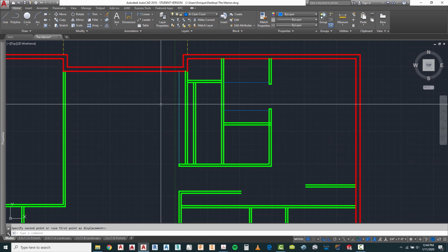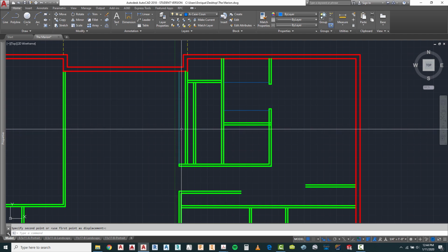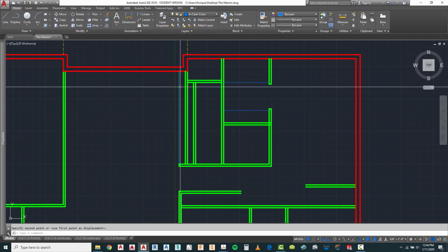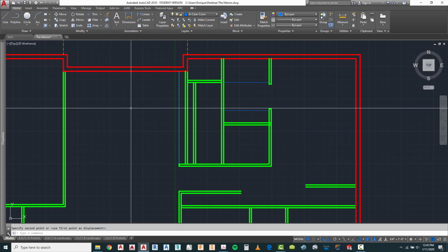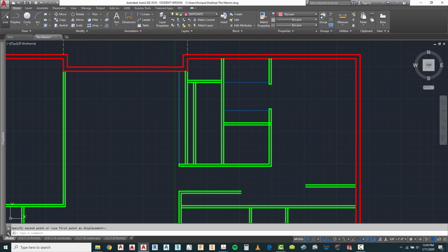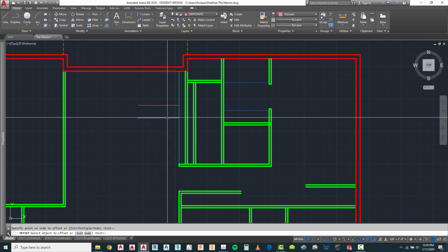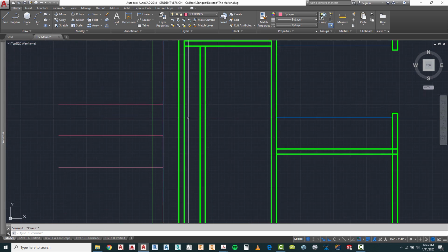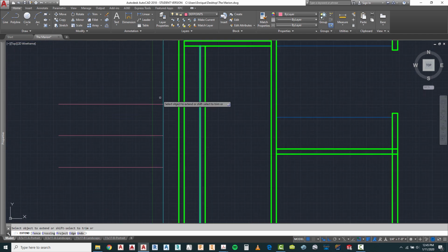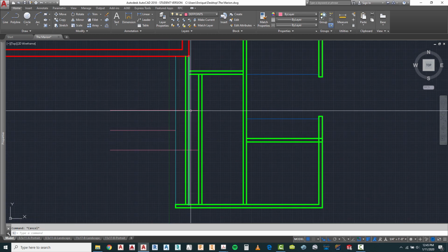What makes a lot of sense in the fireplace in here is we don't have a big house, so we're not going to have a huge fireplace, but we probably want to center it on this shelving in here. So we can go once again to maybe a depth point layer, which is a non-print. Find the midpoint in here, and we're going to offset 2 feet in each direction and extend those 2 lines up to there. That is going to represent our fireplace.